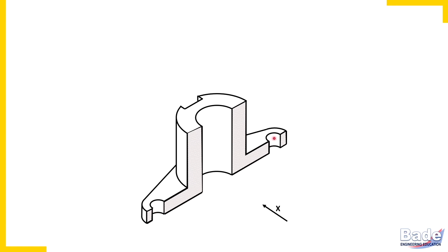Similarly, these two holes on the base plate, inner semi-cylindrical surfaces are revealed now. So some hidden details get exposed because of cutting. But some hidden details, for example this slot, remain hidden even after cutting. So even if we have cut this object from front, the slot on the back side is still hidden.